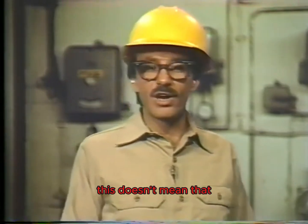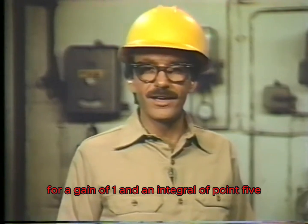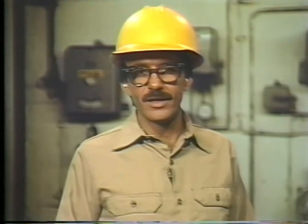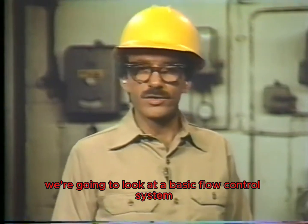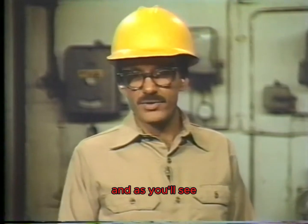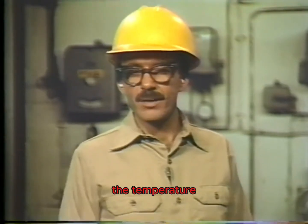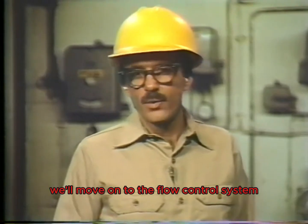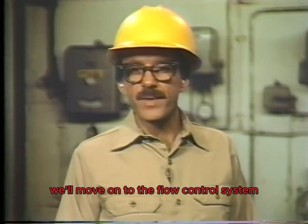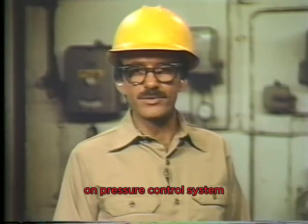Now, this doesn't mean that all controllers are going to be adjusted for a gain of 1 and an integral of 0.5. In the next part of the program, we're going to look at a basic flow control system. And as you'll see, its controller will be adjusted quite differently from the temperature and pressure controller settings that we looked at. We'll move on to the flow control system after you review the material in your text on pressure control systems.